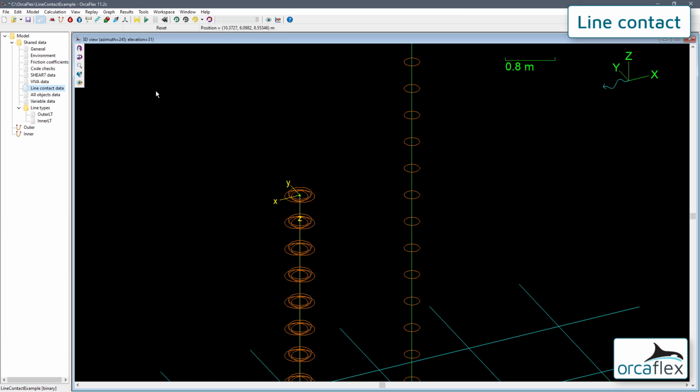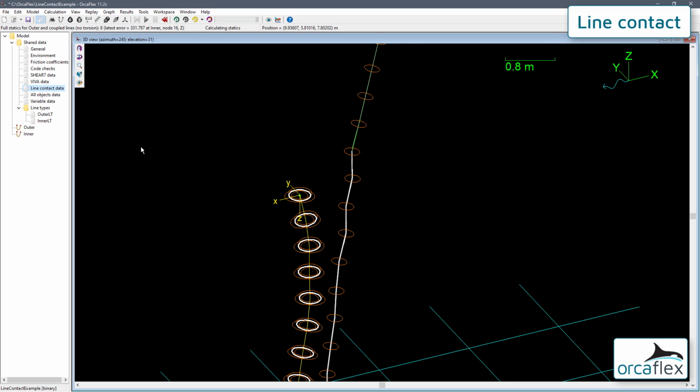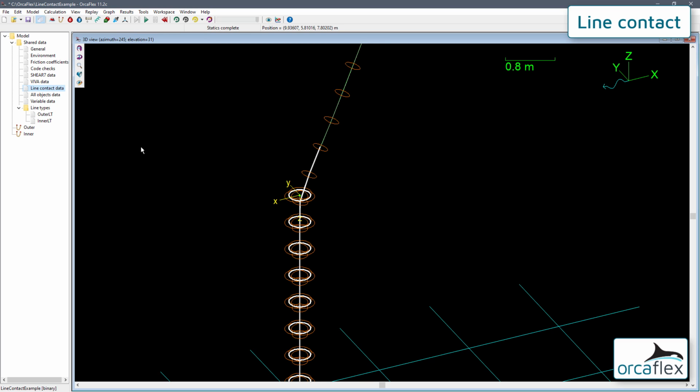Discretizing this model changes the single inner contact surface of the outer line into 3 larger contact surfaces distributed evenly around the original contact surface. We now see an immediate solve as a result of the contact surface being more robustly defined.